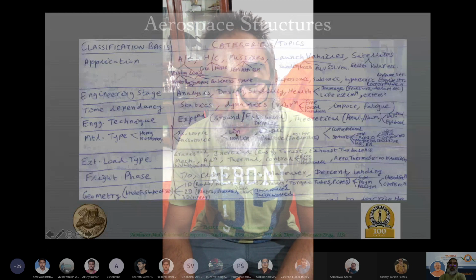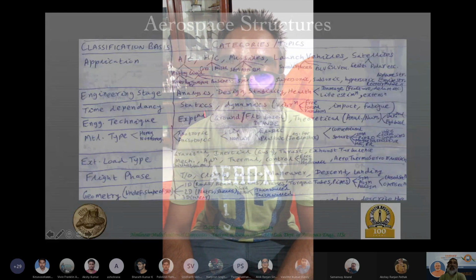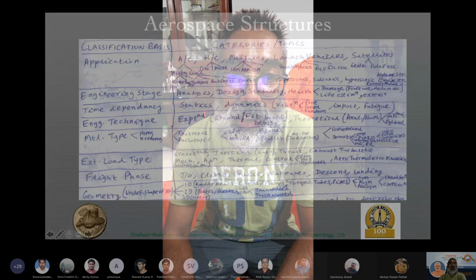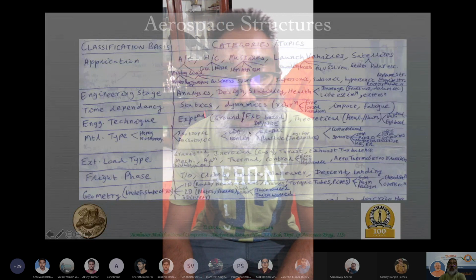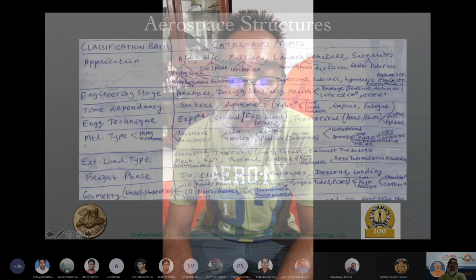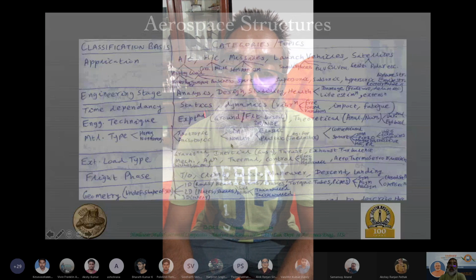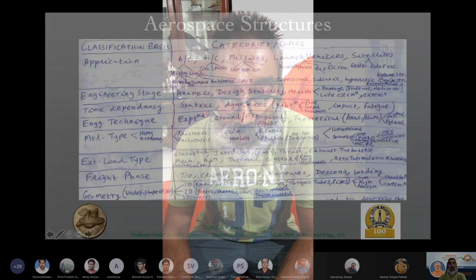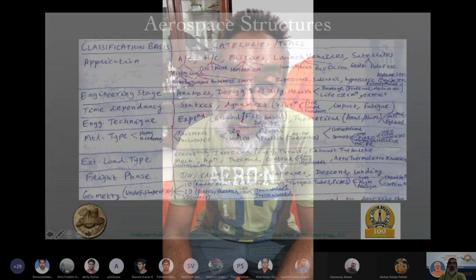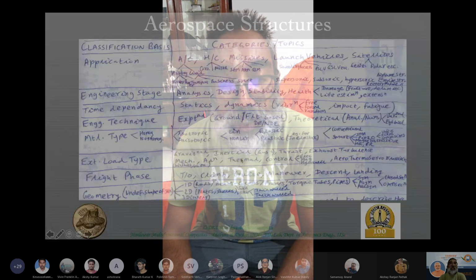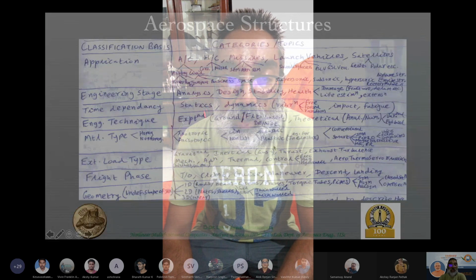Again, the material could be linear. In other words, the stress-strain relationship, even if it might be coupled in different directions, would be linear. In other words, all the elements of that matrix between the stress and the strain relationship are constants. So that's a linear material model. But in general, as the strain increases, you would see that most materials go into a non-linear regime. Especially metals, metal matrix composites. Brittle materials tend to stay linear almost until failure, but there could be exceptions there too.